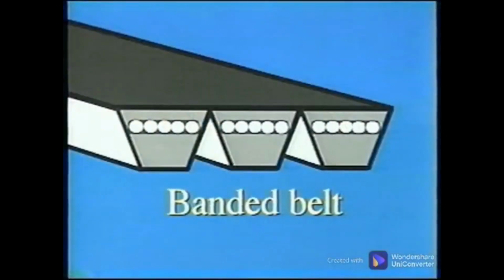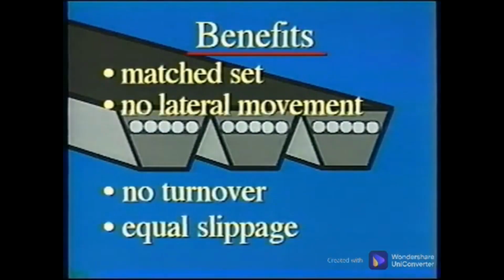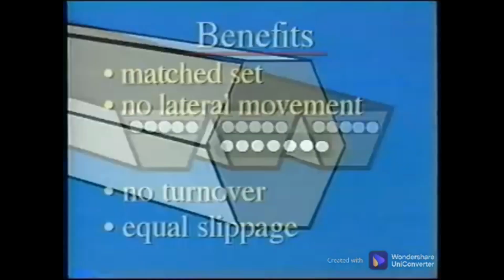The banded belt is used in place of multiple belts. It is several standard V-belts that have a common back. The benefits over multiple belts are: it will be a matched set, there is no lateral movement of the belts, there is no belt turnover, and the slippage is the same for all the belts.